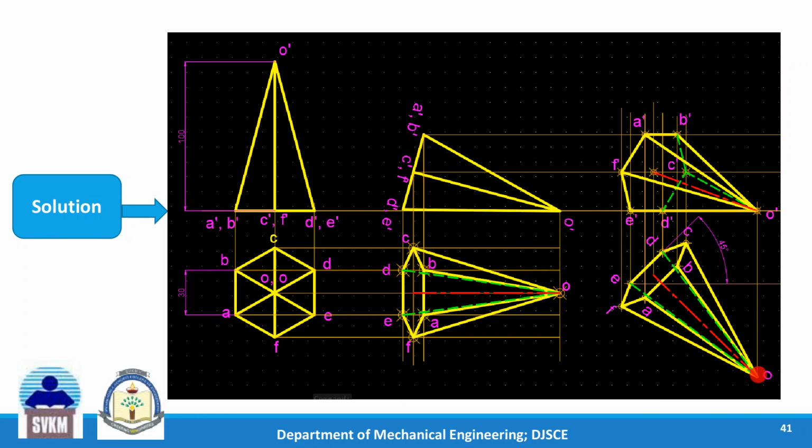Once you draw this in this way, that is, the reorientation is done, then we take the projections for getting the front view. So these are the projections, these are the projectors from the second step front view. Intersection points are connected now. The intersection points are named first, and accordingly the connections are done. See, the consideration while connecting the points: the observer is here. Whatever is nearer to the observer will be connected by object lines.